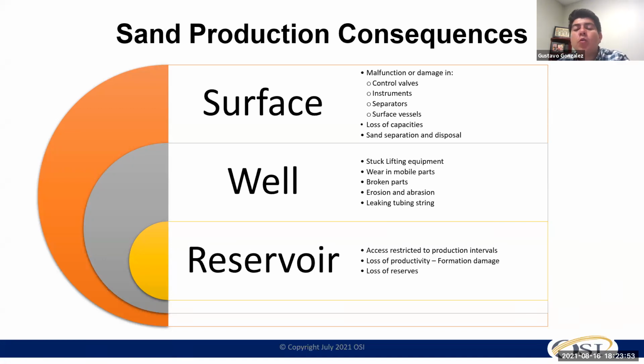On the unconventional wells, I can see the same phenomenon. A lot of sand could start building in the heel, or on the lateral section, and I can see that my pressure is slowly changing and the amount of fluid is decreasing, because now I have a restriction point on my lateral. So some of those is going to cause poor efficiency, and at that point I need to take some actions, either pull the well or wait until it fails and go back and do a clean out.